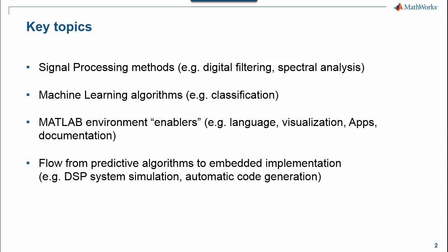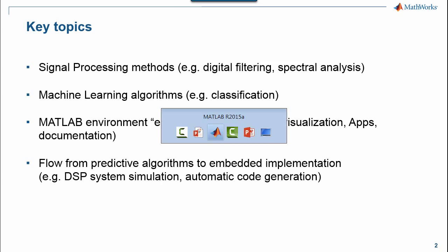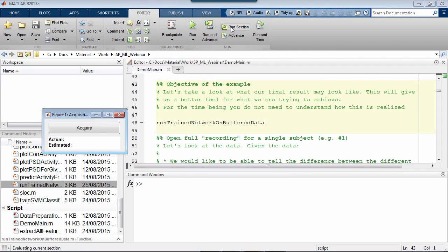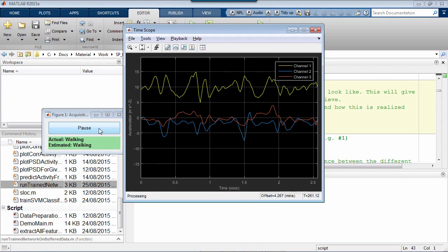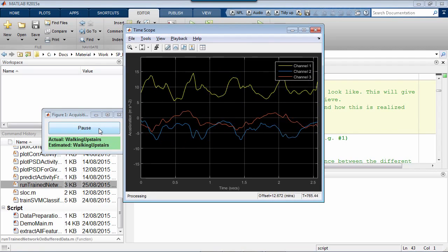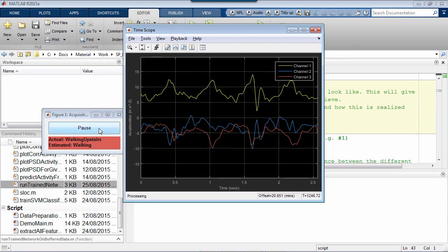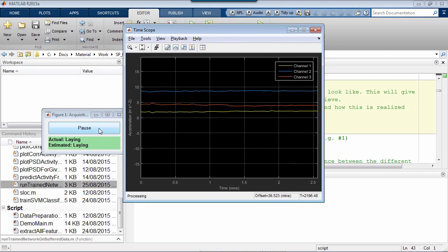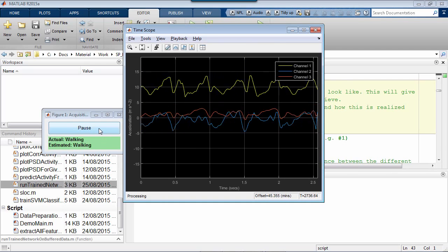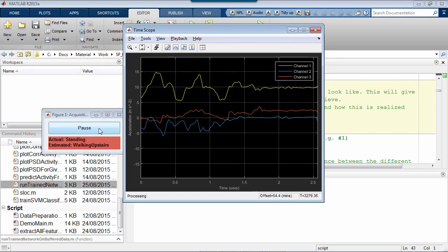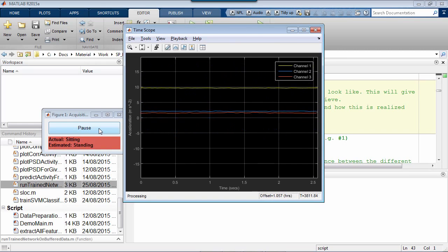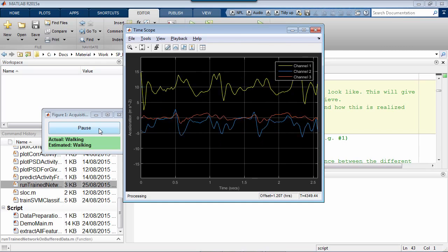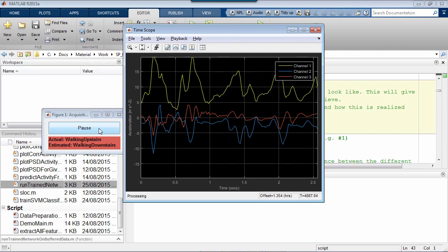Now, I'll come back to the slides later, but I'm going to spend most of this hour discussing a practical example running MATLAB. What you're looking at here are the three components of the accelerometer signal captured using a smartphone. The signals are generated by a subject wearing the smartphone in a fixed position of their body and engaging on different physical activities. We are running an algorithm as if it operated on live signals, but in this case, we're using labeled recorded data for validation.